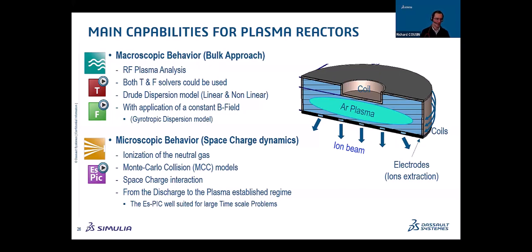Then we can consider the Monte Carlo collision models, which include the elastic collisions and the excitation of the neutral gas. Then we are going to perform a full space charge interaction directly from the discharge to the established plasma regime. We can fully control how the plasma is established in the plasma chamber, and the ESPIC solver is well suited for this kind of application.